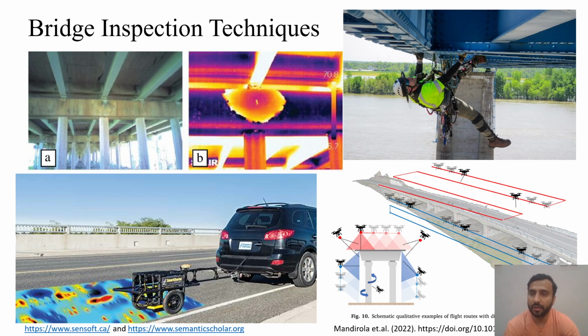The longer span may require a very big under-bridge inspection vehicle for access to its inaccessible components. So in Japan, they use the Ninja technique, through which a climber uses ropes and other safety equipment to reach the inaccessible components for visual inspection.